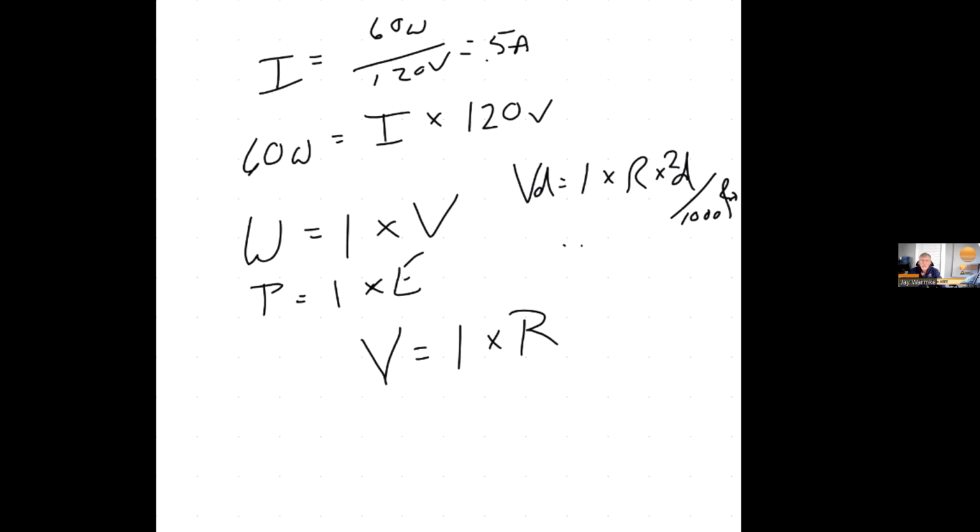So if I want to figure out voltage drop on this example, let's say that my amps, remember the amps on a single panel are going to be the amps for the whole string, because when you hook things up in series, voltage goes up, but amps remain the same. So if I've got a solar panel with a 9.35 amp IMP, and I hook up 10 panels in a string, well, then the amps of that string is still 9.35 amps. So I'm going to just use that as an example.